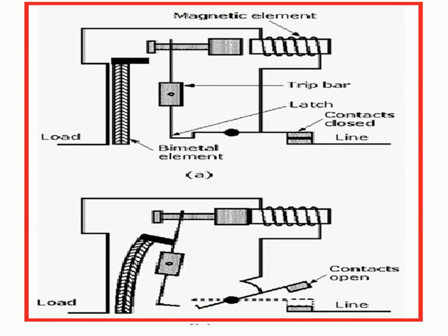Here the diagram shows the working principle of the MCB. The MCB may be operated by two conditions. Either it is a thermal circuit, or it is a magnetic circuit, or some designs have operation of both, that is, a thermal bimetal element and a magnetic circuit, as shown in the figures.